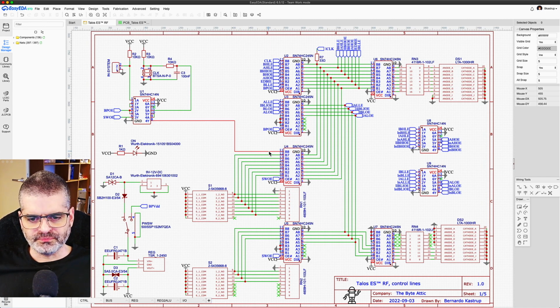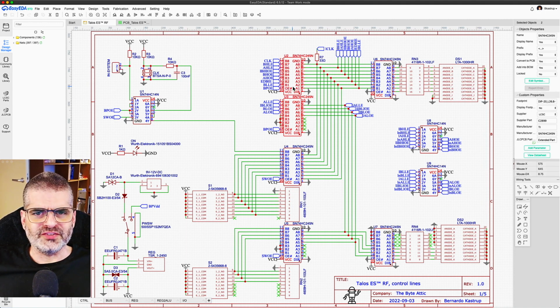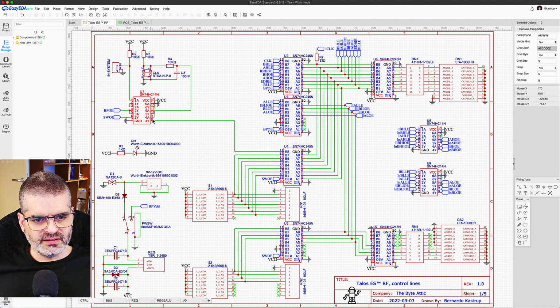local clock. There is another buffer here on top, which has the system clock coming from the backplane in case we want to use the board in system, and you select one or the other by either activating this buffer or this buffer. Actually, you either activate these 2 buffers when you are in system, or you activate these 2 buffers when you are in standalone mode, and they produce the same control signals. So the clock is produced here by this little debouncing circuit.